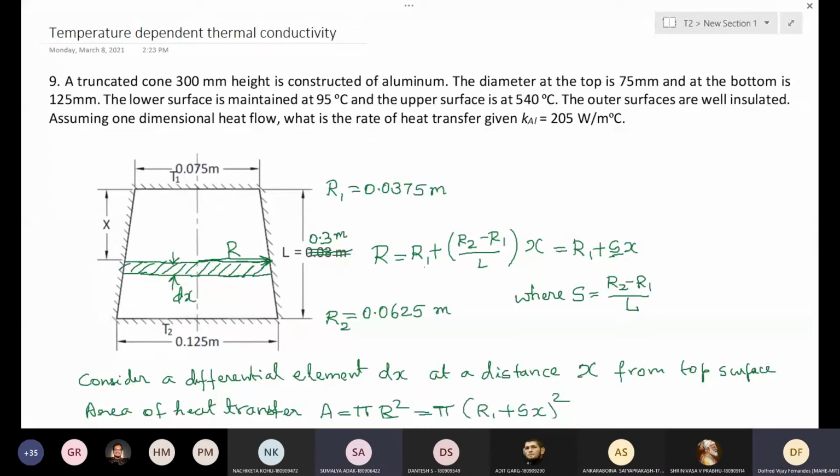Yes, sir. And the thickness of the insulation which has the same heat transfer as the bare wire is 5.136 millimeter. Not thickness, radius, sorry. The radius of the insulation R2 is 5.136 millimeter. So for the thickness, you have to subtract the radius of the wire, and you'll get the thickness.